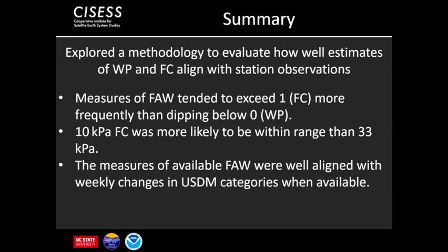When we looked at fall, I didn't get into this in the presentations, but almost every single station depth, the fall tended to exceed 1 more often than go below 0, which indicates that our fractional available, our field capacity is perhaps too low for the measurements we're getting from the CRN records.